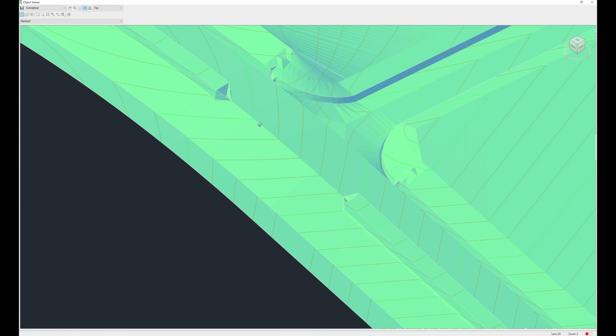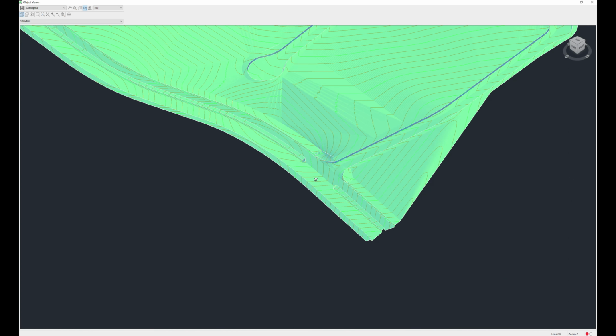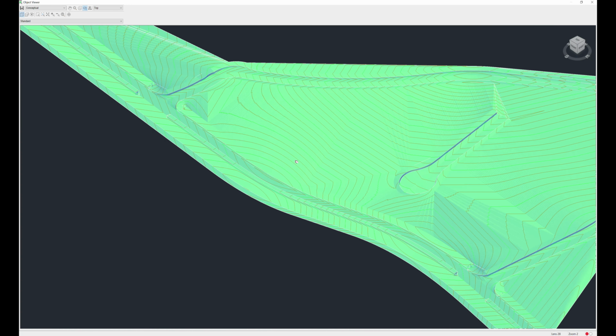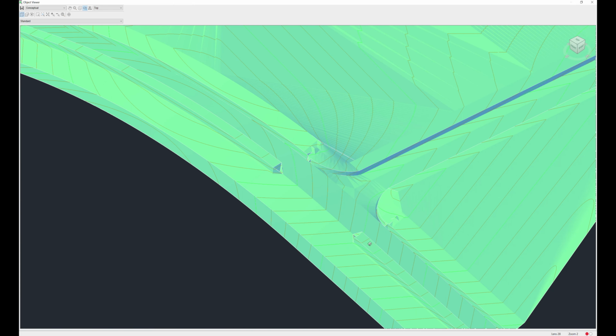So we've added that east intersection in now. We have a nice transition from our primary collector to the east side. We have a transition from the primary collector to the west side. We didn't have to fix the assembly again because we did that in the previous step.